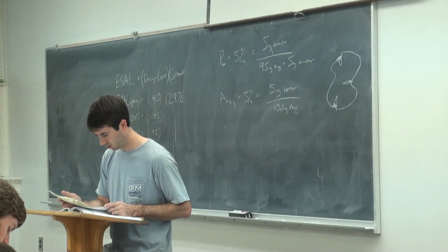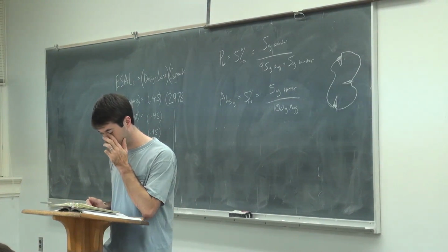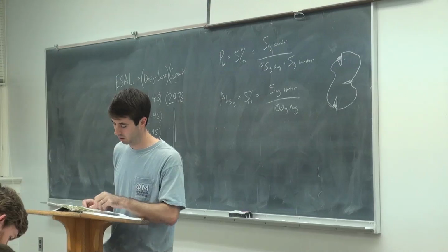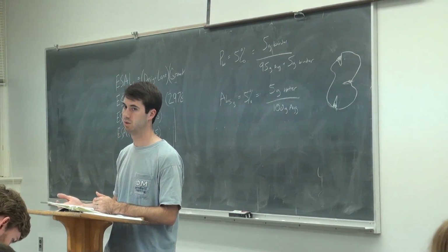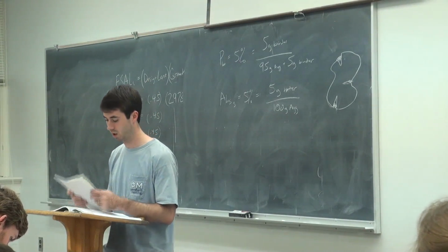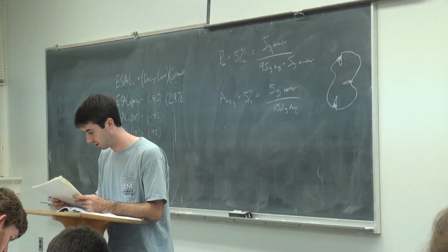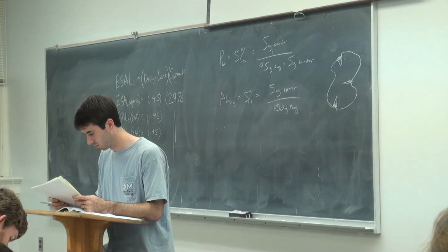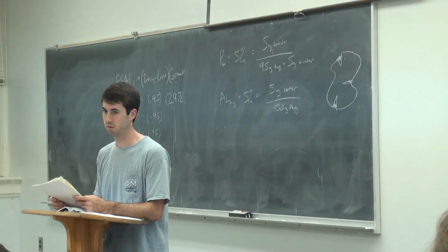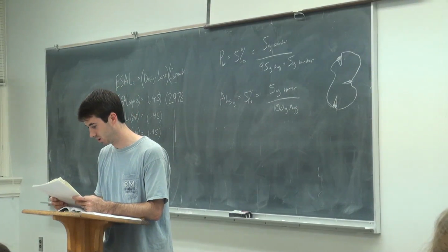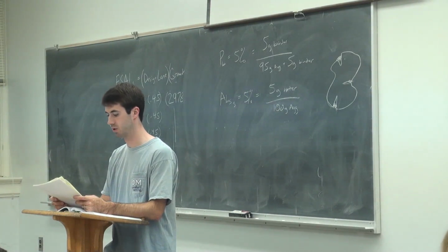Your angularity, that next chart down, basically there's a trend. As you increase the traffic level, you have to increase the angularity of the mix. Any ideas why? Reduce rutting. Reduce rutting, exactly. So they become more stringent as you go along. Flat and elongated particles, you know what that is. Just in age. Exactly. And then clay content, as you get more and more traffic, you want less and less clay fines in your material.